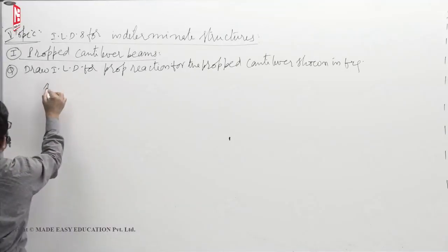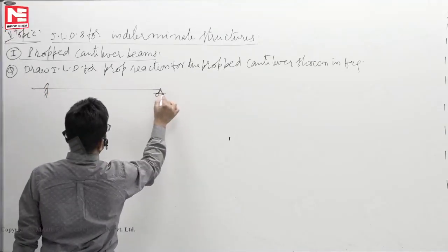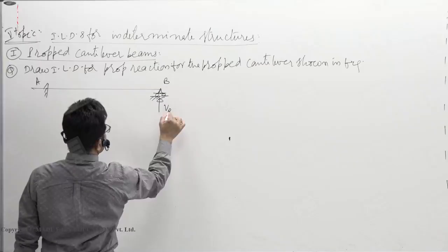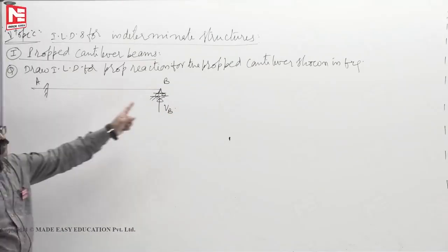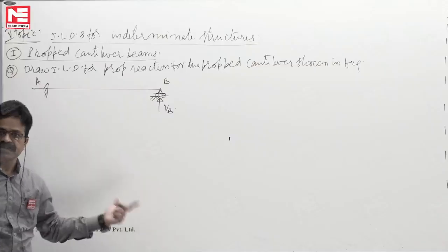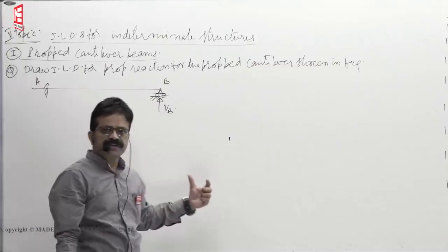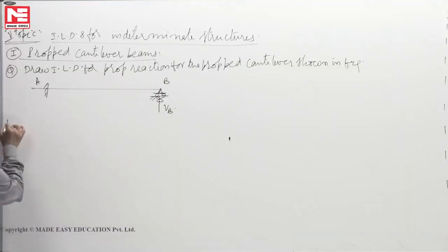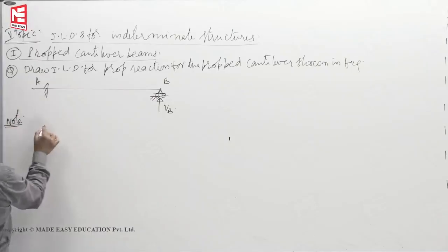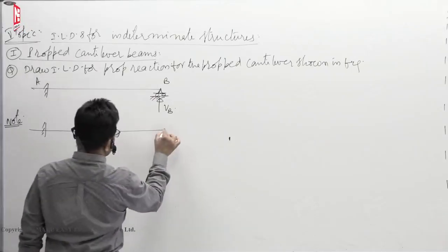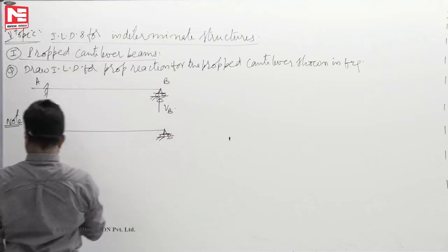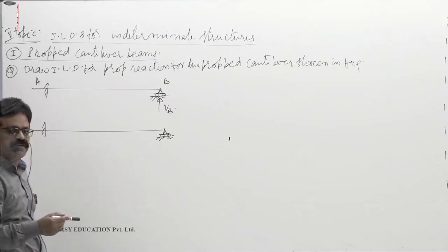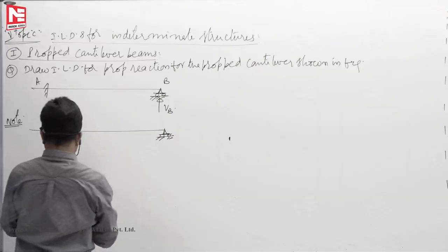Now assume that you are given, say, a propped cantilever A, B. For VB, we want to show when the load is moving from one end to the other end, how the reaction VB gets influenced. If you draw that influence as a graph, we call it an influence line diagram. So what we do is we take some general position. First, strength of materials will take it, then we'll see how to simplify.